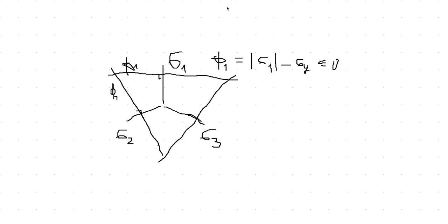And this is an illustration of Phi3. So when you're computing, let's say, the optimality condition for the Lagrangian, which is equal to minus dissipation plus the sum of all these 3 plastic multipliers times Phi1, 2, and 3, each one multiplied by its own multiplier, the problem goes as follows.